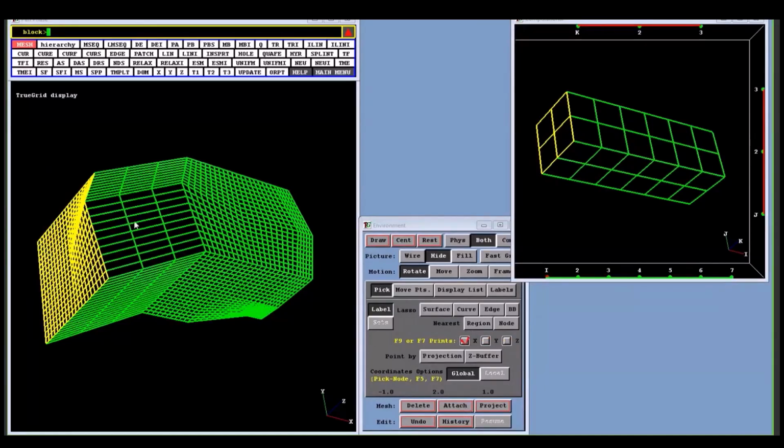And so I select a node. That's one way of doing it. I want this face to be moved so that all of the X coordinates have this coordinate. So I've selected the face, I've selected some form of geometry, and I click on Attach.